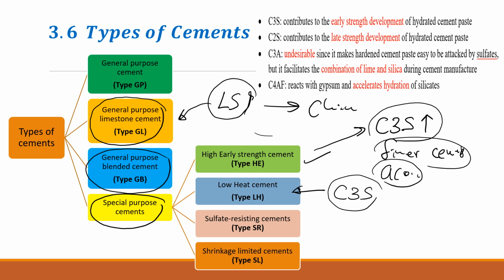Why do we need to control this? Sometimes we need to control it. Why? It can cause cracks. So how do the cracks occur? Why does the heat generation make cracks? It's not settled yet, it's not towards its full strength, probably. Also, when we heat up any material except water, it expands. When we cool down, it contracts. Thermal expansions and contractions with the temperature changes. This heat generation is only when the reaction is happening, so it cools down after some time.